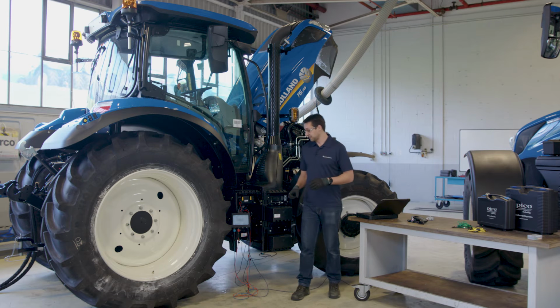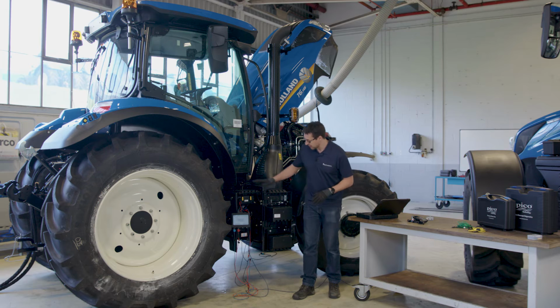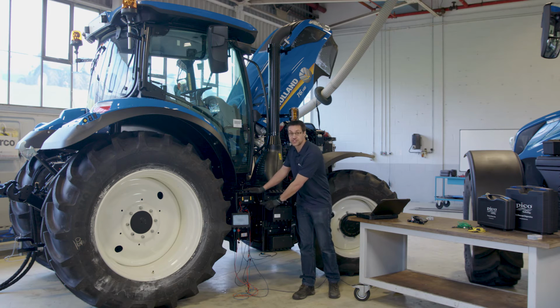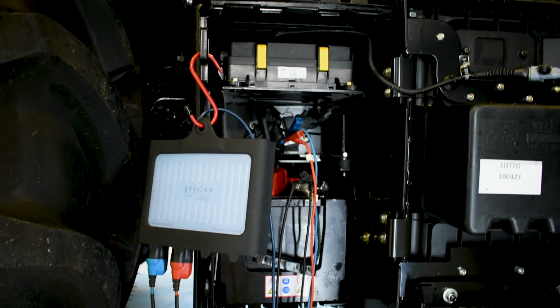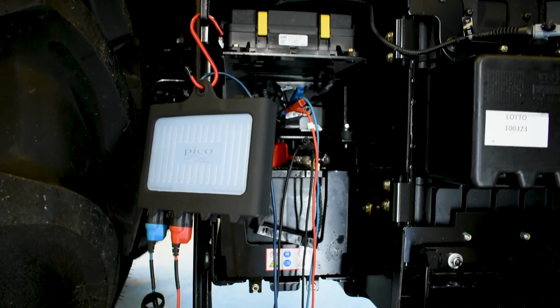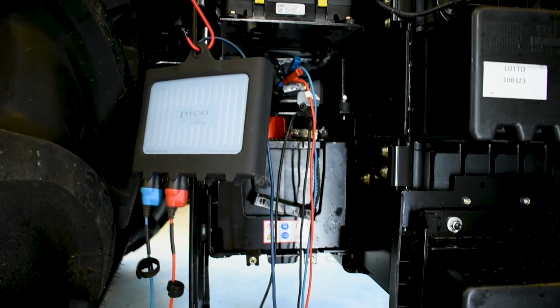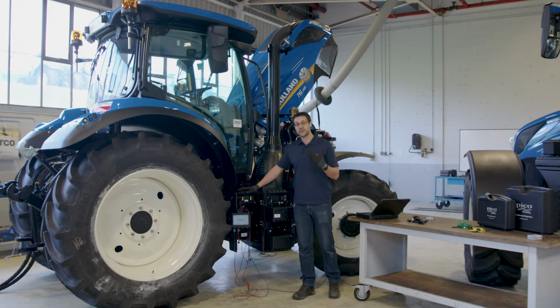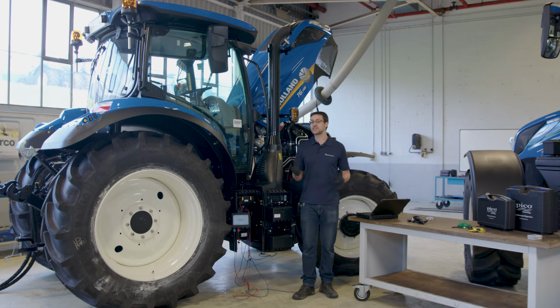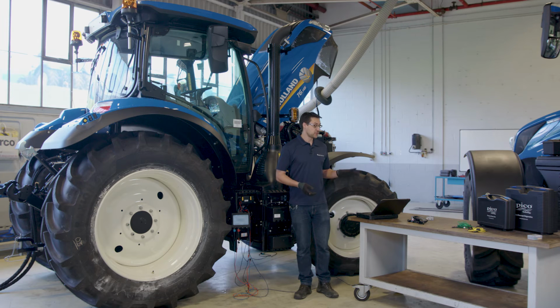Now, I've picked quite a fairly basic one here. So underneath here, we actually have one of the knock sensors for the after treatment system. Now, I've literally just back-pinned into the CAN high and CAN low signal on there, and then that will give us our information. So it will give us our raw voltages. We're not going to do anything massively different with how we capture. So there is a guided test for J1939 decoding, which we will load in. Once we have that loaded, it will give us our references, our known good, what we typically look at.